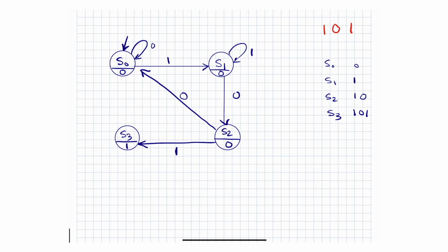So you have 1 followed by 0 followed by 1. What if you get a 0? If you get a 0, I need to see that I got a 1 followed by 0. Well, according to that, 1 followed by 0 is S2. So all I have to do is say, all right, I think that makes more sense now. S2 is 1 followed by 0. And then you get a 1, you get back in here. So 1, 0, 1, 0, 1, 0. That actually allows the overlap.